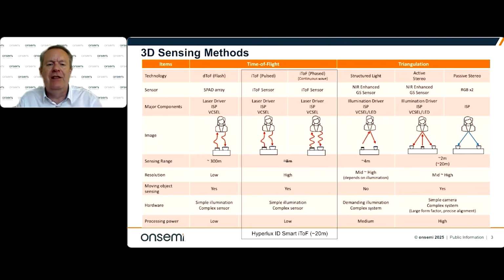The determination of depth is done by the distance between the cameras and a parallax between the cameras themselves. So it has a varying level of depth capability and has advantages and disadvantages. It goes up to normally a few meters. It struggles a little bit beyond that, depending on what type of cameras you have and what the lighting is and what the subject is. But generally, passive stereo is fine.